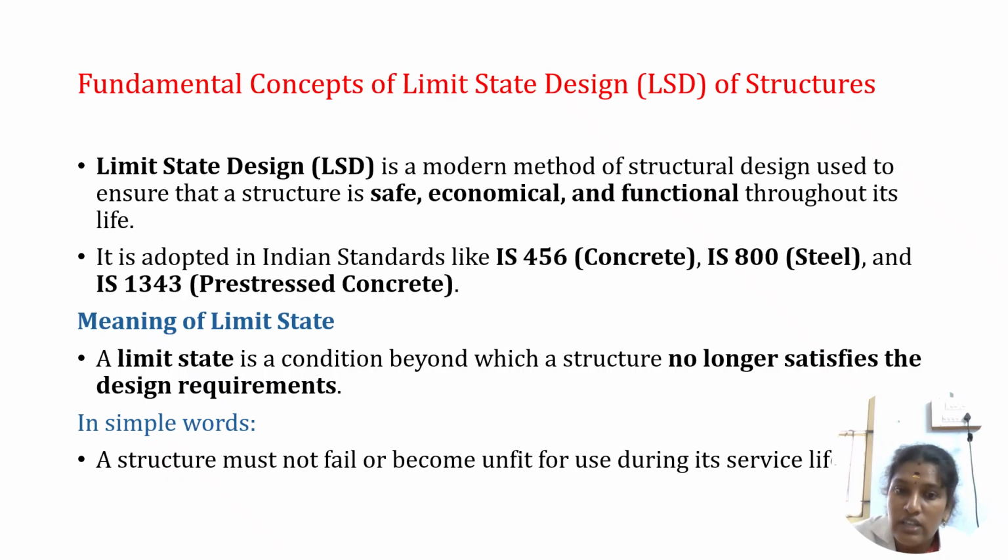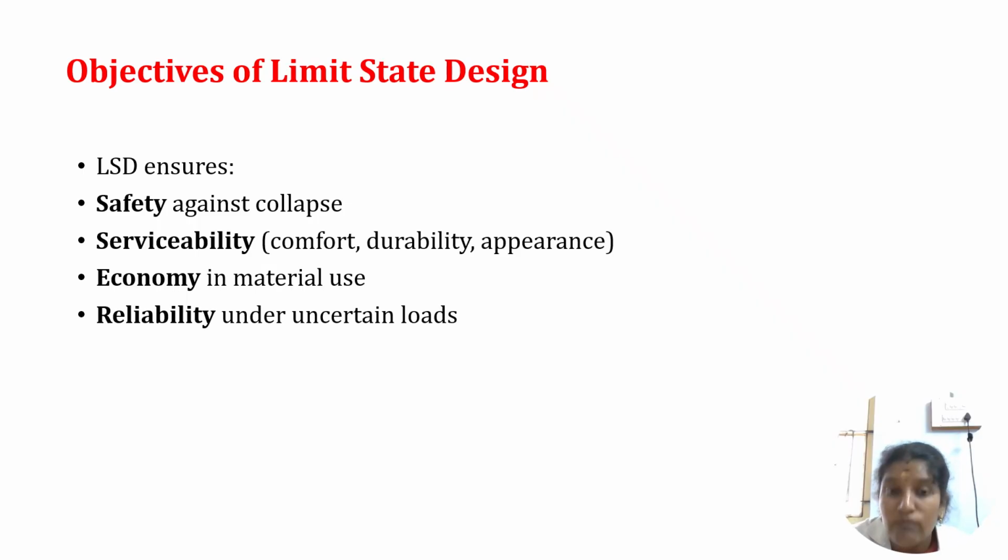We have different Indian standards: for concrete IS 456, which we already know, for steel IS 800, and for prestressed concrete IS 1343. These are the limit state conditions for these kinds of structures. In simple words, the structure should not fail under any condition. That is the main concept of limit state design.